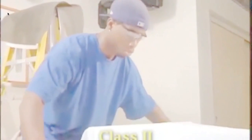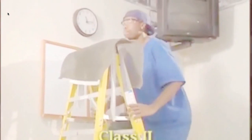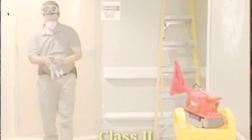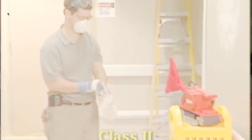Class 2 requires active means to prevent airborne dust and dirt from dispersing into the atmosphere, such as sealing air vents or using dustless equipment. Drop cloths may be used to cover exposed surfaces, and HEPA vacuums or wet mops should be used as appropriate to control dust. Class 2 projects may also need barriers to contain dust. For example, fire-rated plastic sheeting and tape, or portable containment units may be used to seal off access to the work area. HEPA units may also be needed to contain dust.